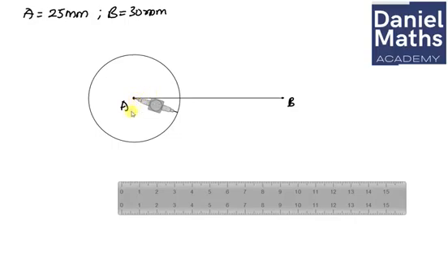So what you're going to do, after you've drawn your circle, is take the tip of your compass. Now let's get it again over here. I'm going to take it at this point, keeping the pin at point B, and then let's reduce this. You can see the number over there, but if you don't want to do that, bring it down here, put the pin at 0, and then extend where you have your pencil.